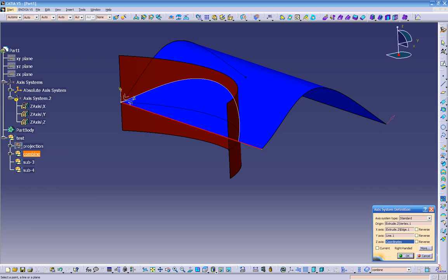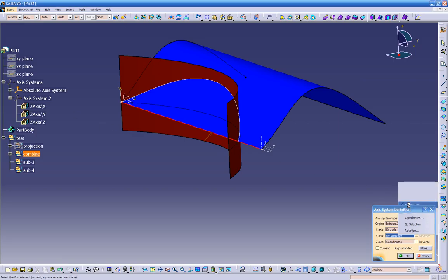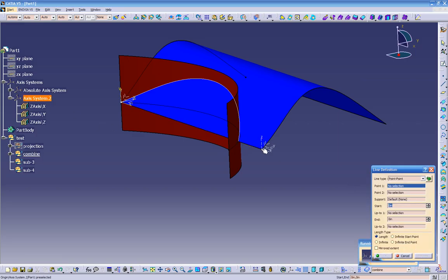The reason we didn't see the line right now is because it didn't like something about it. So we can put no selection, and you can create your line. The reason that we get that little error over here is because when I click on this point, it is the point of the axis. So we don't want to use this axis as a point, we've got to use the geometry.